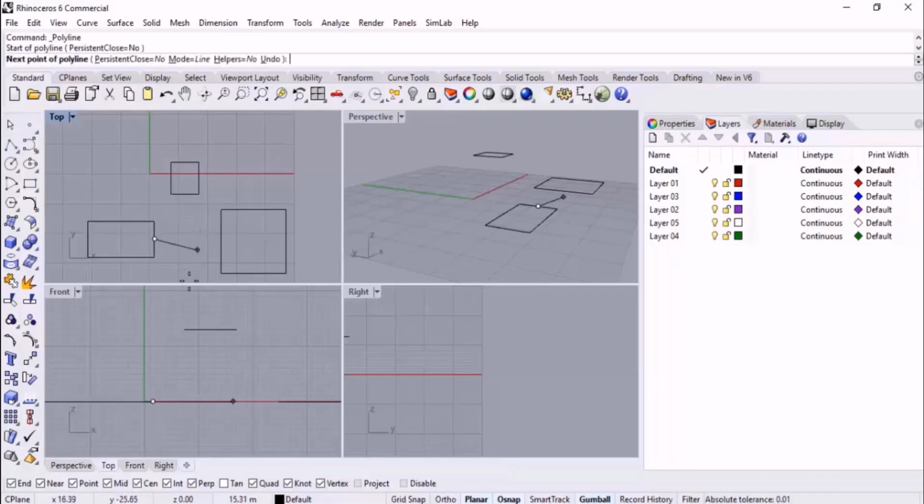So I start the sketching, specifying the first point, and then as I want to sketch the gate, as the point is snapped to the end, it doesn't let me maintain the point in the same plane. Meanwhile, we should enable project in order to prevent snap or to make it ineffective. I enable project right now. Watch this.